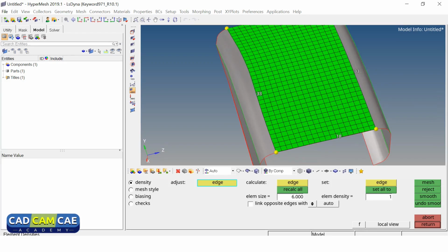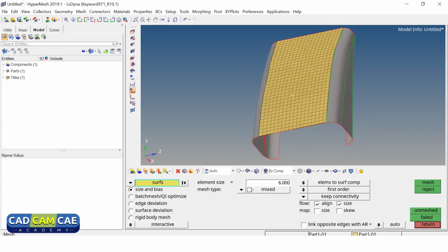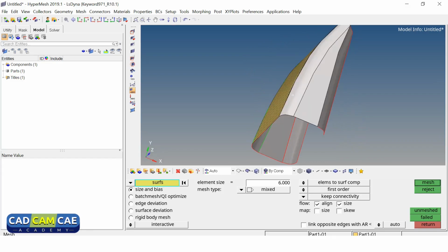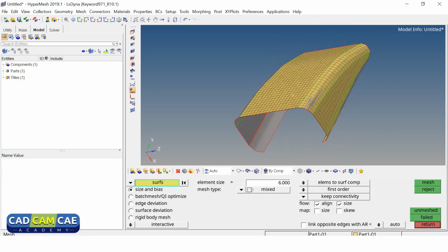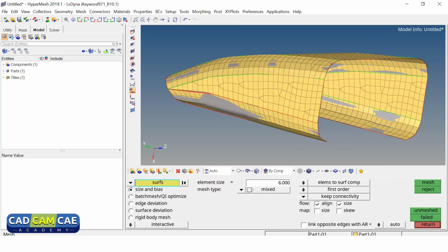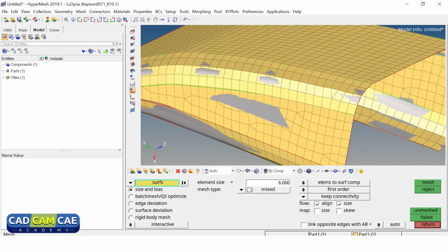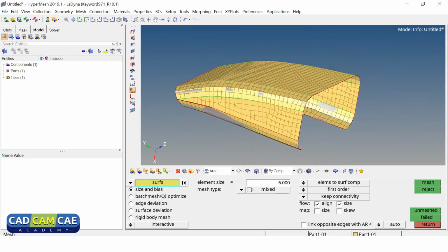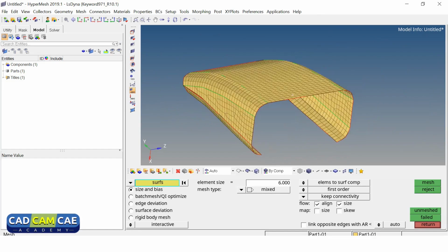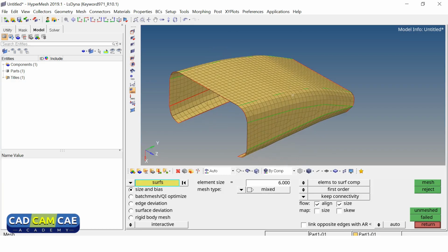See what I mean? Creating a mesh, the very first step of FEA, is discretization, meaning meshing. So this we are going to learn in HyperMesh. See, multiple areas I can mesh. So this is 2D shell mesh. Here two types of elements will be there. We'll see the types of elements in detail: quad element and tri element. So this is nothing but meshing. What is this? Discretization, the very first step of FEA.